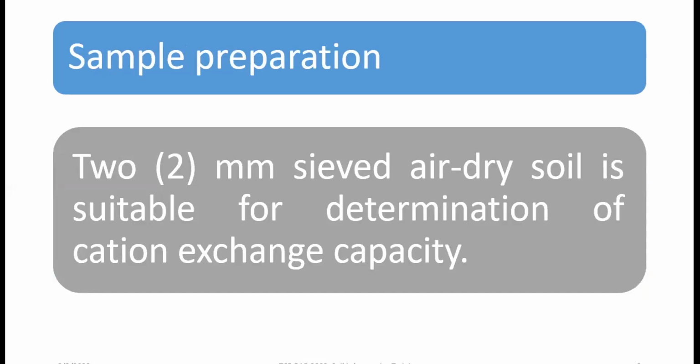For the sample preparation, it is like the ordinary one. You just want soil sieved with 2 millimeter, and it should be air dry.